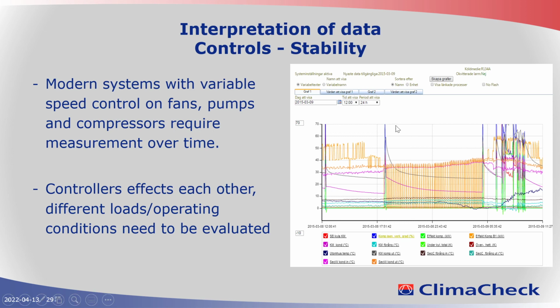And this breaks the screw compressor, and it costs maybe 25,000 euro to repair it. So it becomes extremely costly that nobody checked the system during nighttime operation. Of course, there were no technicians at that time, but if you log a system, it's very easy to see that it's unacceptable and that you need to address the problem.